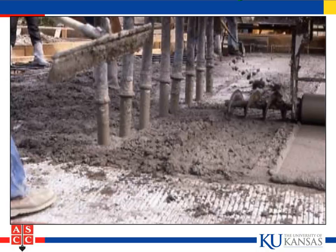Kansas, in general, has less cracking than our surrounding states, and we've been out surveying a number of different states. One of the reasons we feel sure is the improved consolidation. The better the consolidation, the less settlement can occur later on.